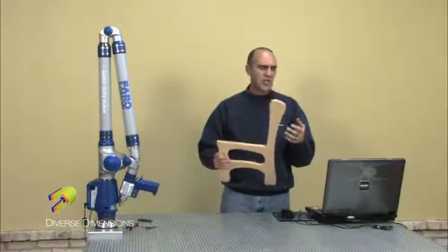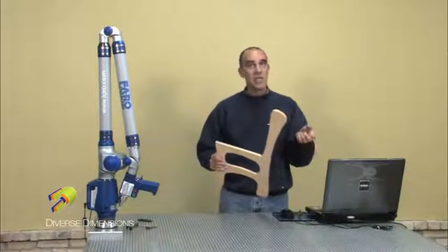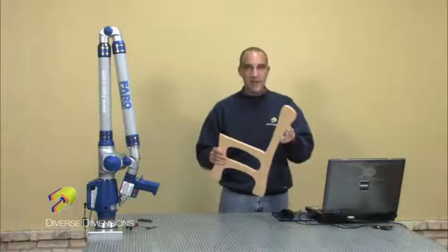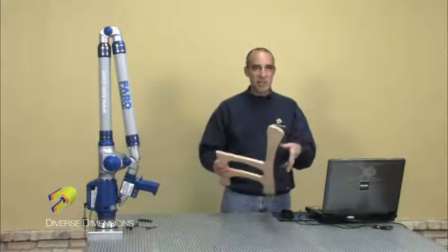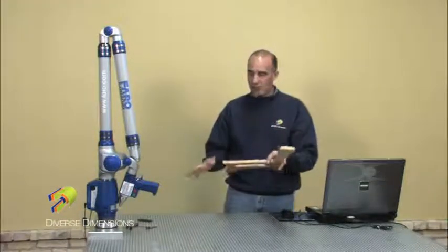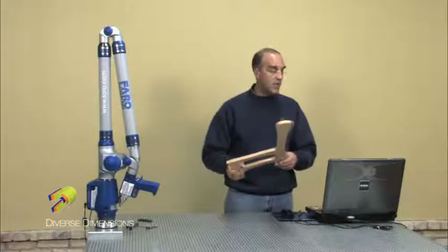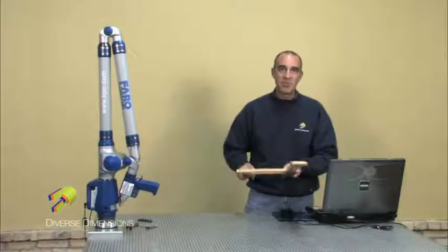But what I usually like to say, though, is test both the splines and the polylines in your CAD system. So once you do an export out of your CAM2 session as an IGES and you pull that in, take a look at both the polyline and the spline in your system just to see what works better for your system. So I'm going to set up a fixture for this, and I'm going to get right into the scan here in this SAT file. So hang tight for just a second while I build up this fixture and we'll jump in.